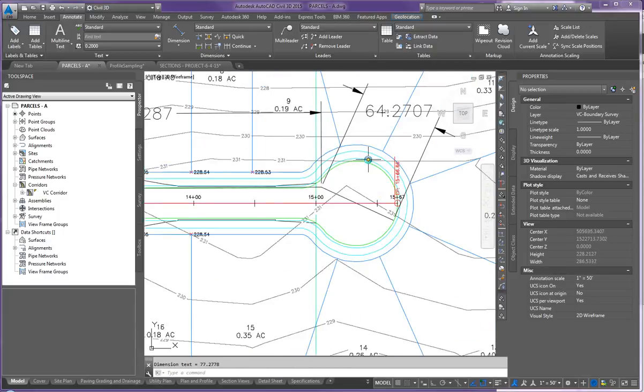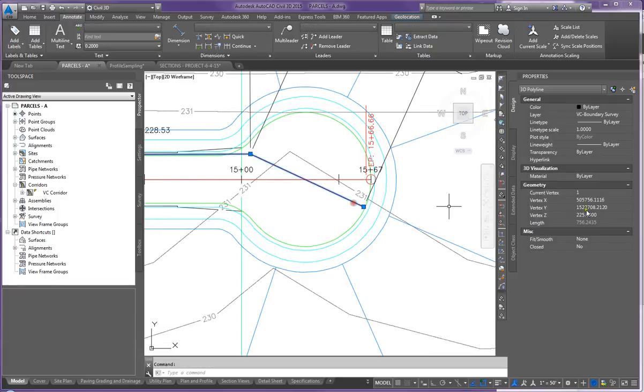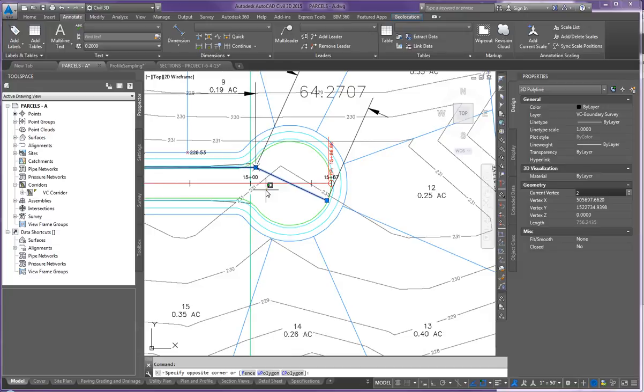Okay, the reason I need these is I need to get elevations associated based on our distance and slopes. We're going to use a continuous slope of 0.5%. So if I highlight this, if I started up here at 225, and pull the next invert down, if I click to 2, then we said over here that was 64.27 feet. 64.27 times 0.005 subtracted from 225 gives me,